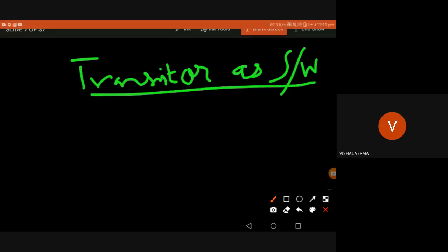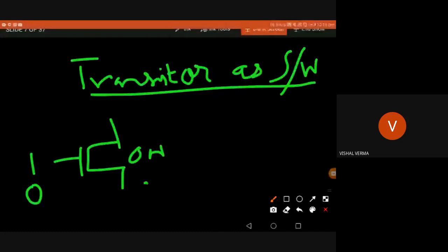as well as its applications. So yesterday we discussed two types of MOSFET. This is the NMOSFET. If input is high or one, it is on. Input is zero, it is off. It has some terminals like drain, source, and gate. The gate terminal is the control terminal. Whatever input goes to the gate terminal, if it is high, the NMOS is on, and if it is zero, NMOS is off.